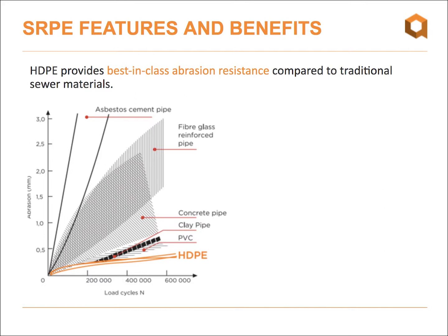They're filled with standardized abrasive slurry and capped on both ends. These samples are then put on a tilting table, and they start creating these cycles by tilting the tables, for several hundred thousands of cycles. And at regular intervals, they will stop the process, remove a piece of the sample, and measure the amount of material that has been eroded away.